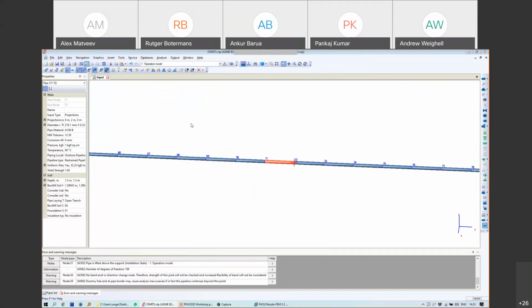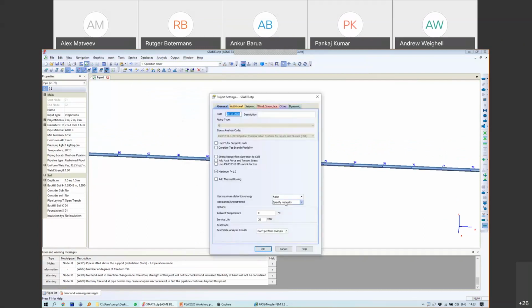We have another feature, auto detect. StarProf automatically checks the axial load and internal force in the pipe, and if it's almost close to a restrained pipe, it will use the equations for restrained pipe. And if it's lower, StarProf will automatically use the unrestrained pipe equations. But the best solution is to use the Star Smart Check calculation.